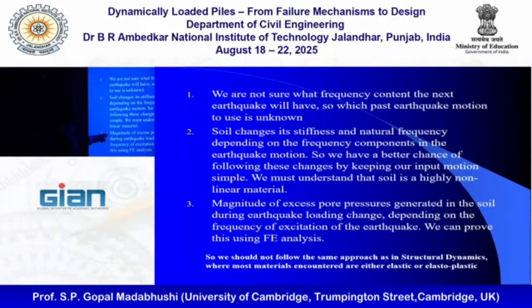This is the other point you are asking. Magnitude of excess pore pressures generated in the soil during the earthquake should be the same as you would get in the field, because pressure has scaling law of 1.